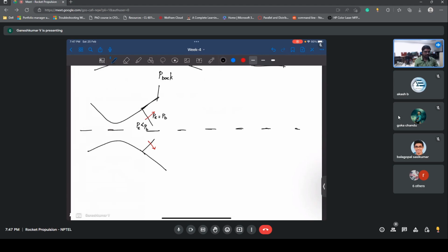We cannot withstand a normal shock. A normal shock requires a very high pressure gradient across the shock. We have a low pressure gradient, so we put an oblique shock, and that oblique shock balances the pressure. So basically, you have balanced the pressure. But what happens? The flow is diverging from the midpoint, so you need to conserve the mass. So this is one of the reasons.